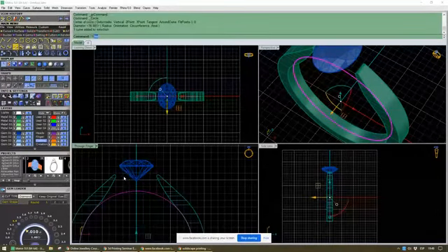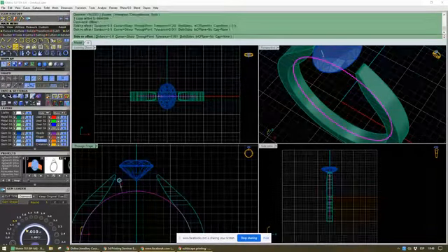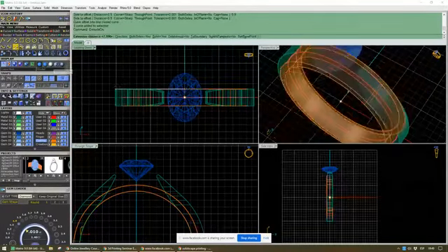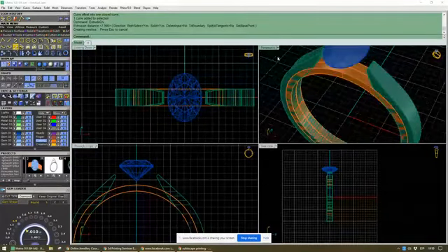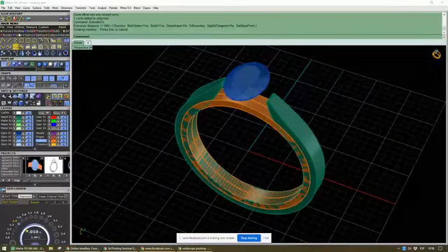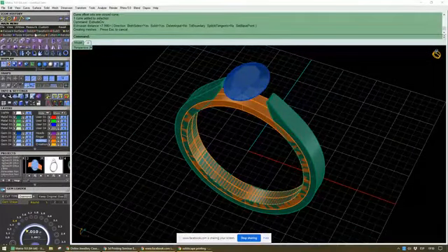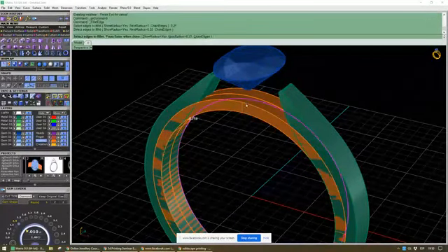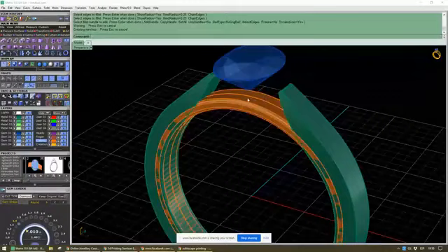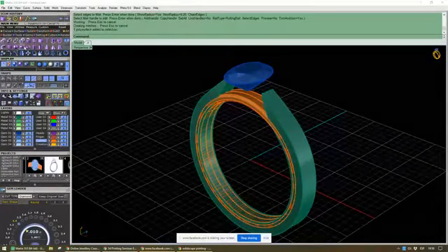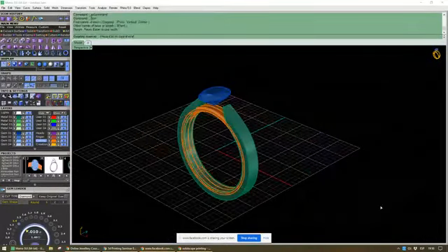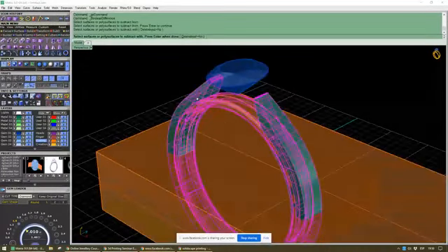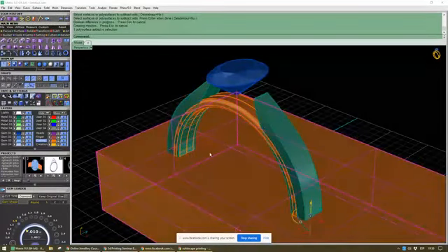Bridge here could be 9, and I can just extrude it, kind of like this. And now what I can do, for example, is make the edges a bit softer, like this, and now chop it in half by making a Boolean difference.